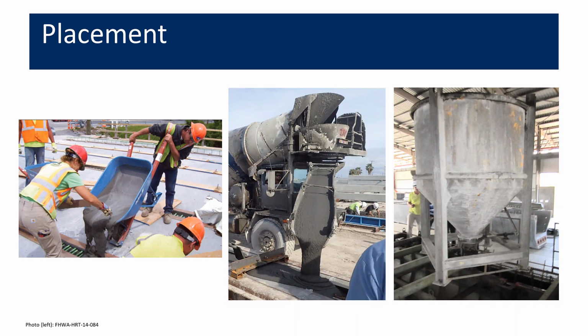The UHPC is typically self-consolidating, and so it can be placed and handled in ways that one typically does with self-consolidating concrete. However, because of the silica fume and the low water cement ratio, the mix does tend to be a little bit sticky. And so it just takes a little bit longer for that self-consolidating process to happen.